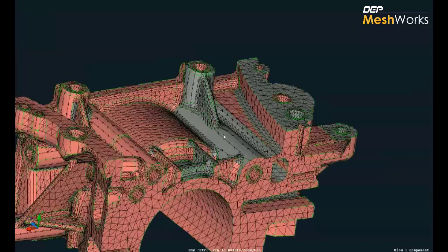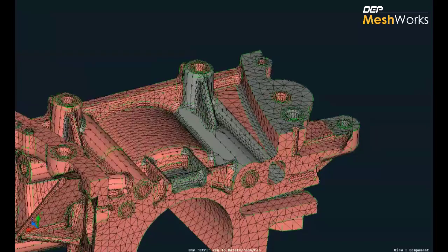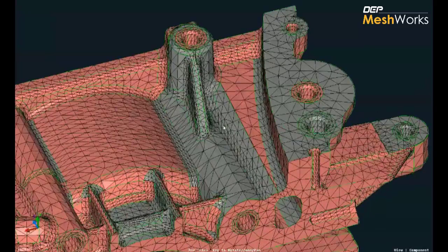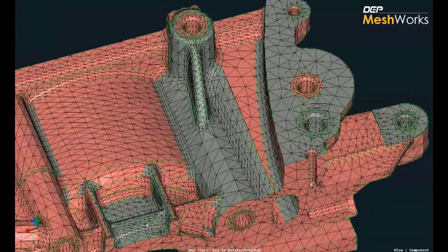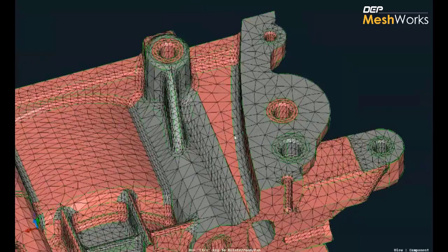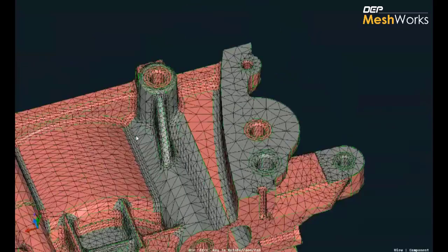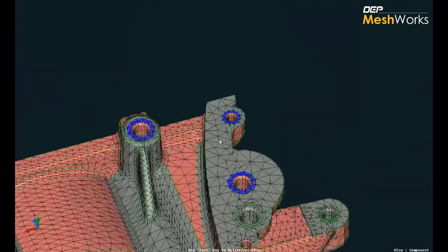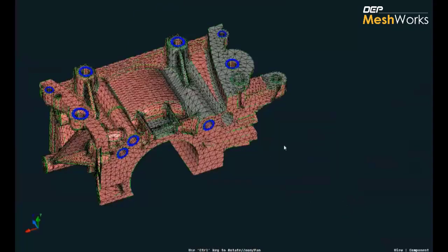Let me switch off the... So as you can see, the mesh, wantedly given different element size on the fillets, and the meshing looks all well and good with all connected regions. And then if I am to switch on the surfaces, even in all the changed surfaces, so this is typically a modified region or a changed region, the surface also gets updated. So this is one very good thing about the associative modeler.